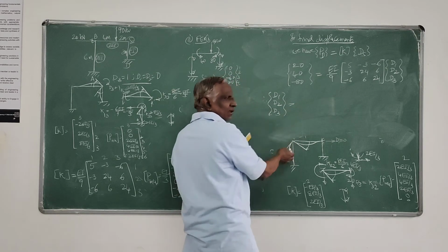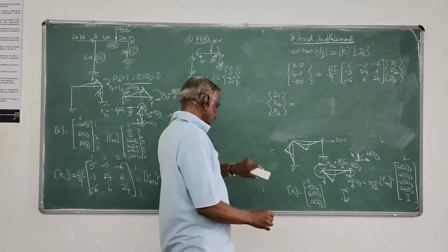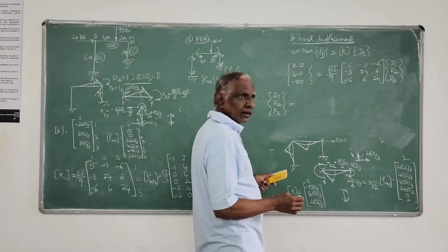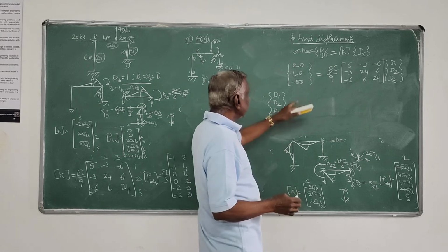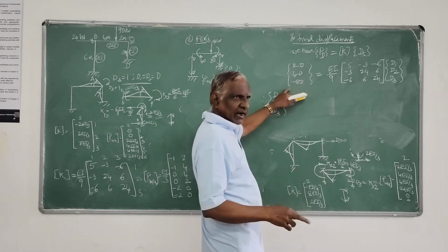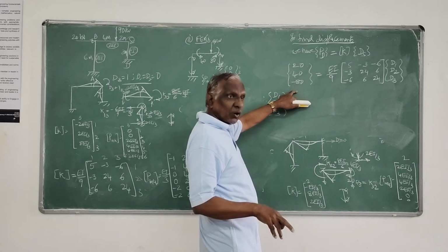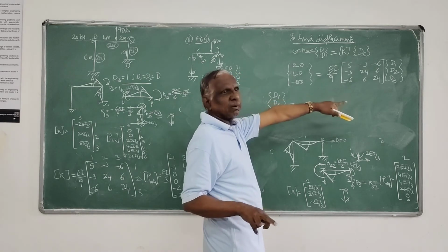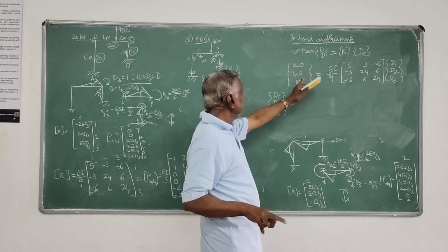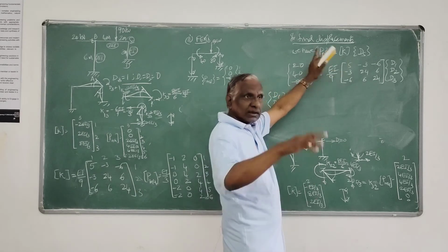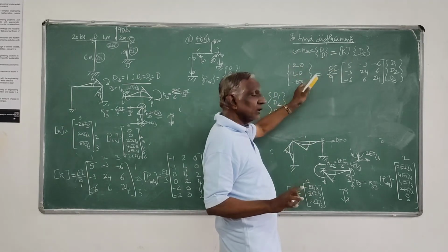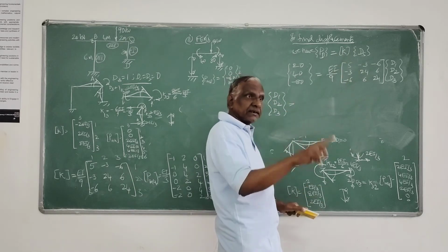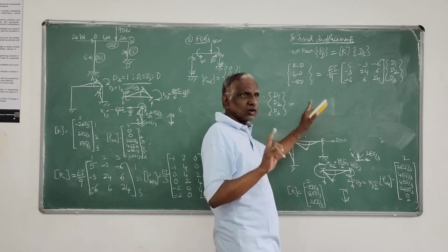Whatever we have to determine, we are determining straight away. The PD matrix also depends on D1, D2, D3. Which one? PD matrix. This PD depends upon that only. D1, D2, D3 correspond to equivalent joint load. I told you, equivalent joint load corresponding to unknown displacement, because that we are using here. Not the PMF and all those things. It is only the equivalent joint load corresponding to unknown displacement, which is PJ minus PMF. You have to be careful.